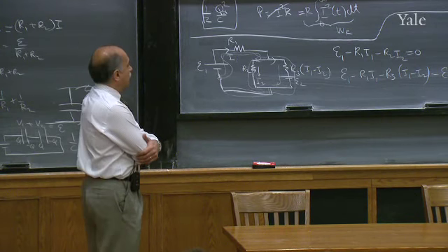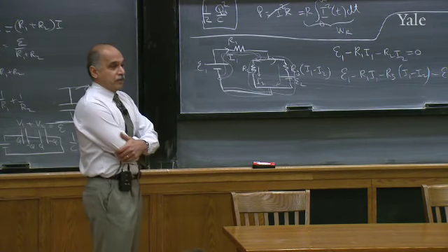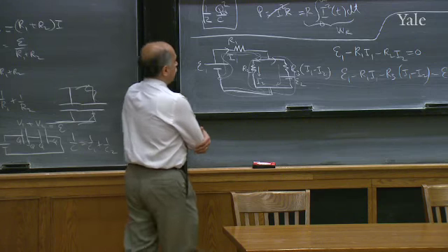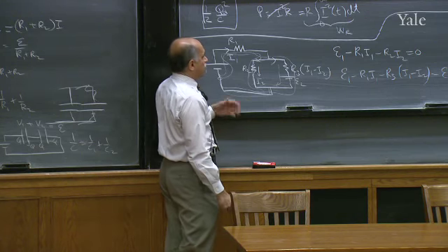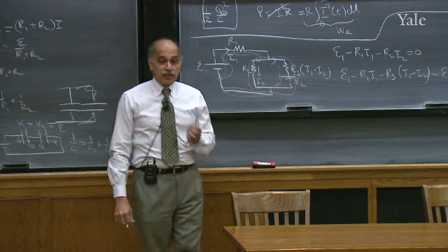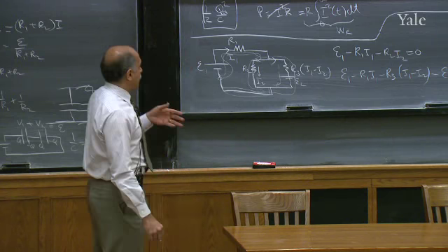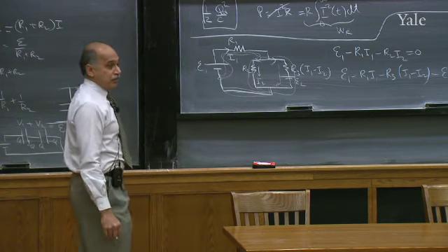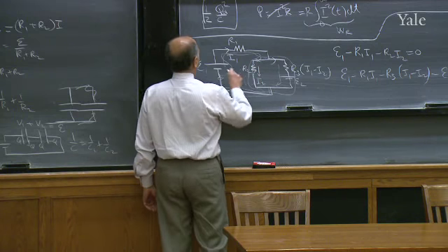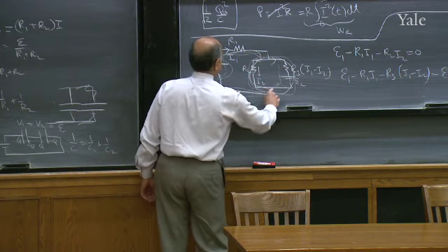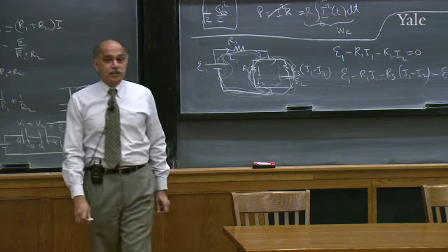It'll always turn out that if you've got two unknowns, you need two independent equations. If you can get 3 and 4 and 5, you will find out they are not telling you anything new. So that's when you stop. If you don't know that, you may start writing all kinds of equations, right? You may think, hey, here's another loop. Here's another one I can do. You can do all that, but you'll keep getting the same stuff.